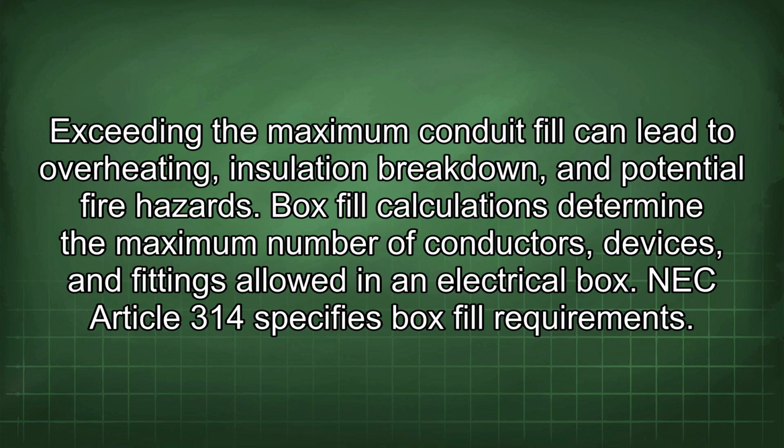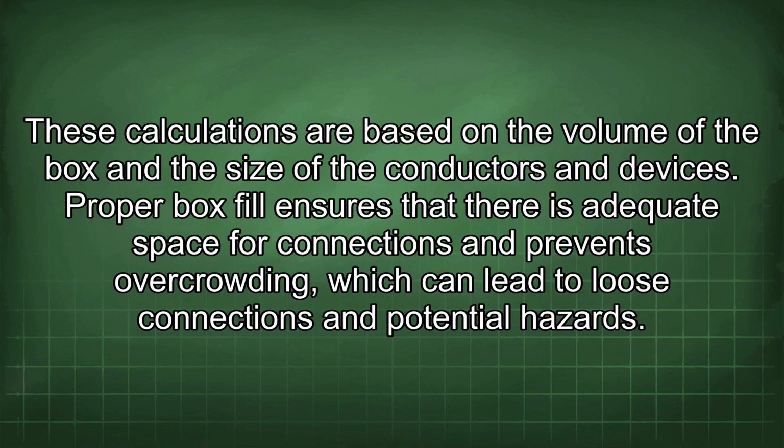Box fill calculations determine the maximum number of conductors, devices, and fittings allowed in an electrical box. NEC Article 314 specifies box fill requirements. These calculations are based on the volume of the box and the size of the conductors and devices. Proper box fill ensures that there is adequate space for connections and prevents overcrowding, which can lead to loose connections